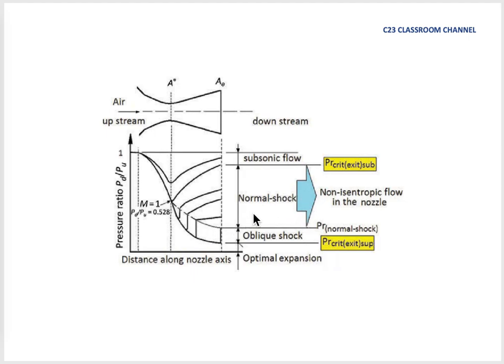And in shock waves we have two types. We have a normal shock wave, which is perpendicular to the flow or to the object, and the oblique shock wave, which has a certain inclined angle. We will learn about the normal shock wave in the next lesson. So I hope you could read a little from your textbook about the idea of the convergent divergent nozzle. The most important thing in a convergent divergent nozzle is that at the throat we need to have Mach 1, and then we need to do something to make sure that after the converging section we could get velocity more than Mach 1.